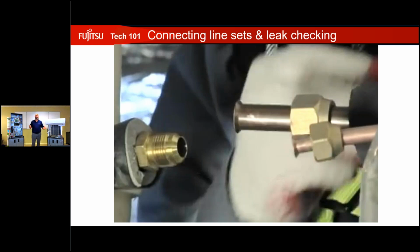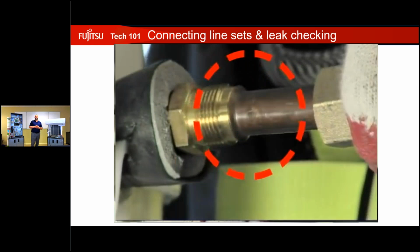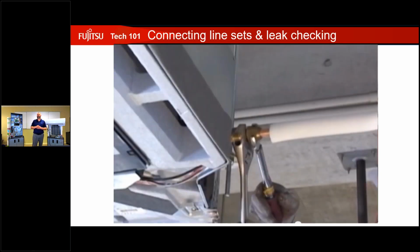Like I said, the main part of your installation errors is going to be right there at that fitting. You can kind of see the process as they go through it here. There's the face of the nut onto the face of the flare, holding it in place, hand tightening that brass nut, and then torquing it down to make the final connection.